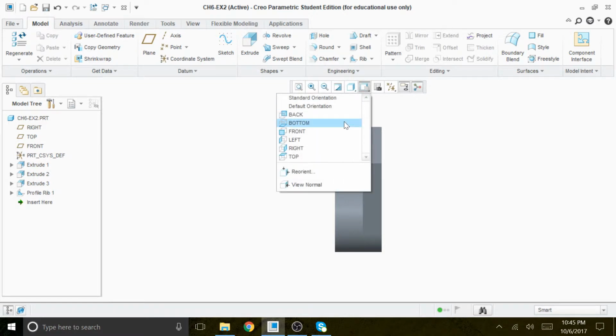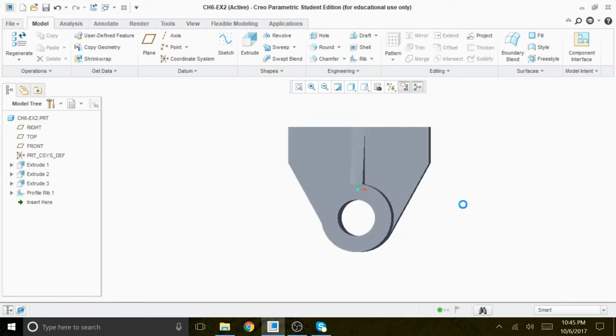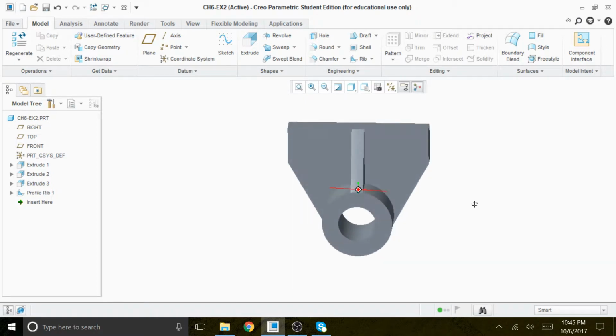And if I wanted to look at the front view, because someone in the class asked me, how do I know which plane to place this? For every solid model it is a bit different. You have to make a decision, because this software is created for designers. So as a designer, you should be able to decide which view to begin with. We call it the sketching plane.